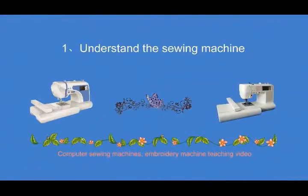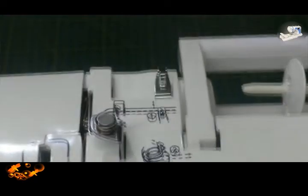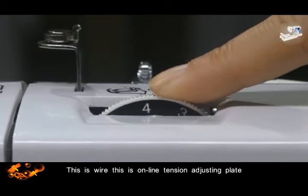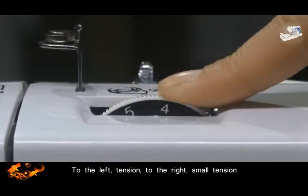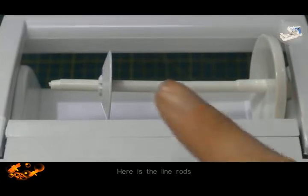One. Understand the sewing machine. This is the wire cover. This is the wire hook. This is the wire slot. This is the wire. This is the line tension adjusting plate. To the left, more tension. To the right, less tension. Here is the line rod.